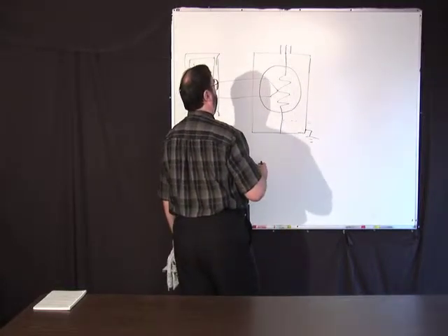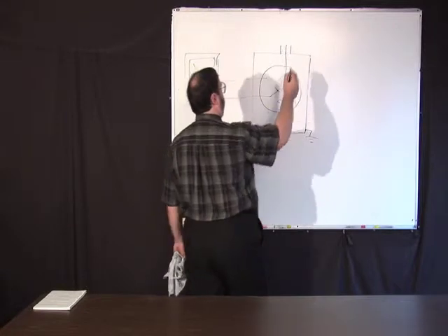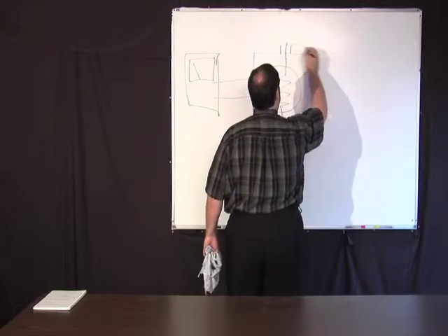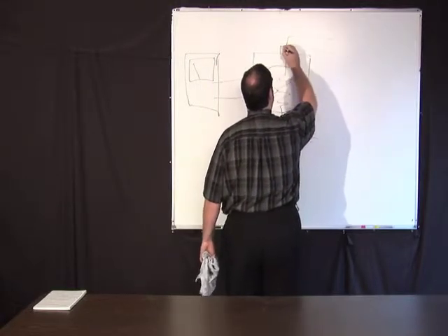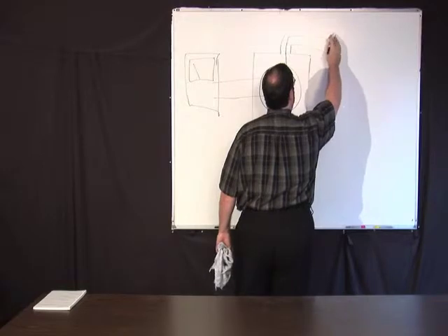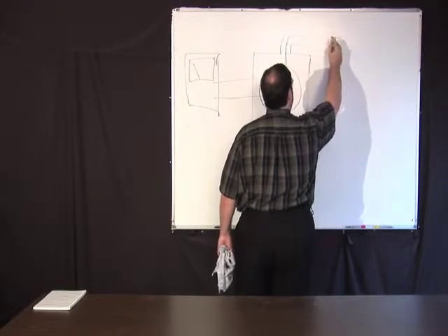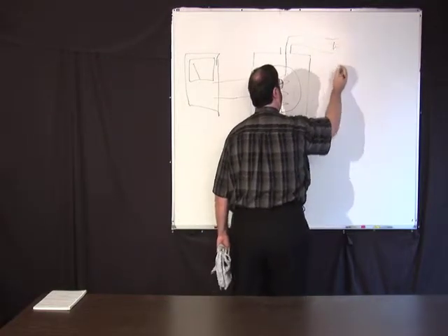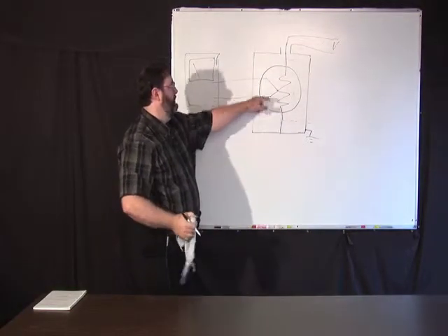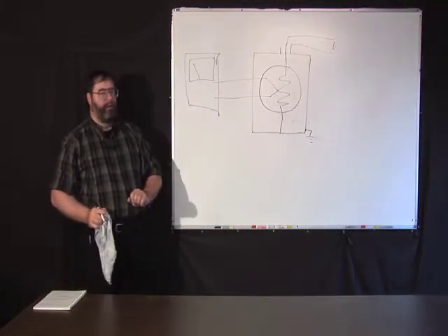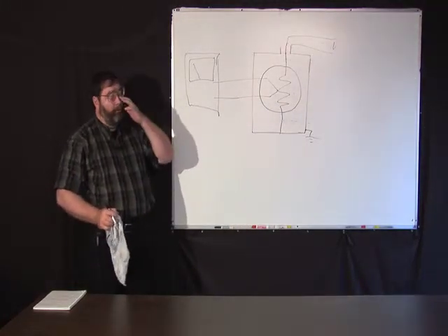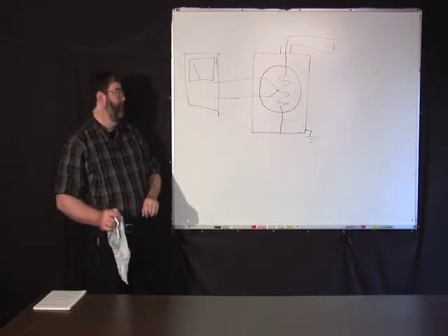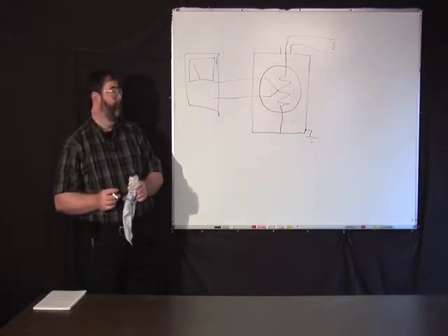And what happens is that you put some sort of voltage between here and here. Now, how should I draw that? You put some voltage here. It'll heat up the resistor, and it'll result in some sort of indication here because there's going to be some heat there. This is called a thermal voltage converter.